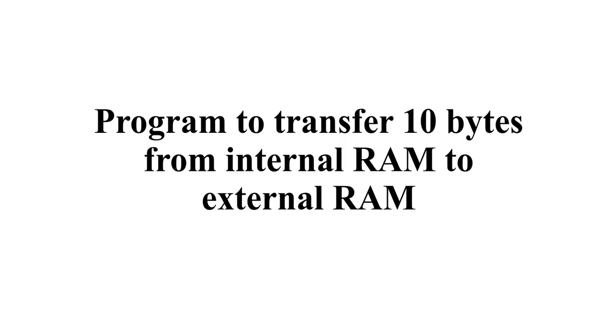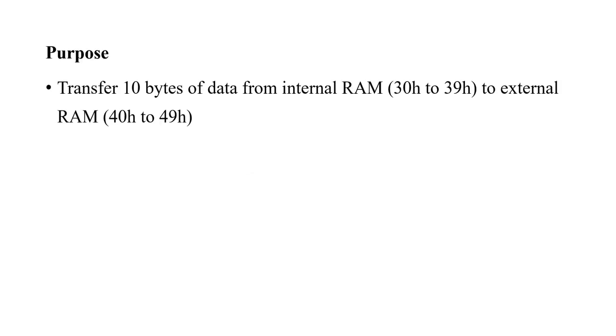Today we will see a 8051 program to transfer 10 bytes from internal RAM to external RAM. The main purpose of the program is to transfer 10 bytes of data from the internal RAM locations, that is, we have selected the memory locations starting from 30H to 39H, to the external RAM. For external RAM, we have selected the memory locations starting from 40H to 49H.